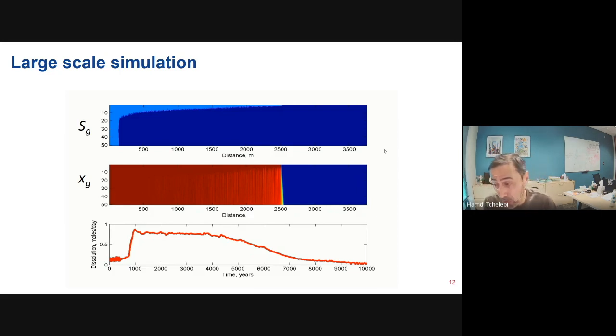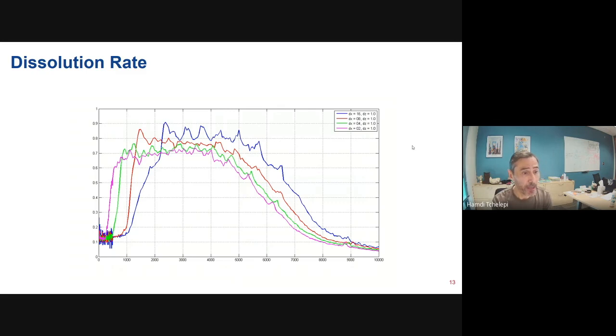That is to look for very large subsurface aquifer systems that are not necessarily completely closed, but where you can secure large amounts of CO2 injected safely if you know how to balance the amount you inject with all of the trapping mechanisms to prevent the CO2 from staying mobile after a certain period of time. So again, the dissolution rate, the amount of CO2, is a very strong function of getting the dynamics right.